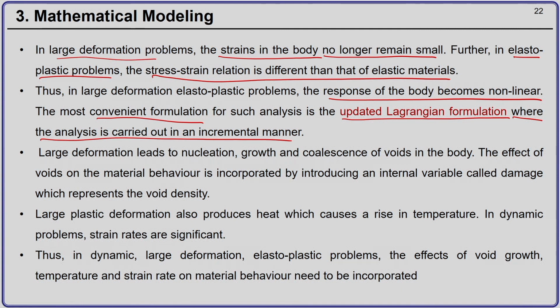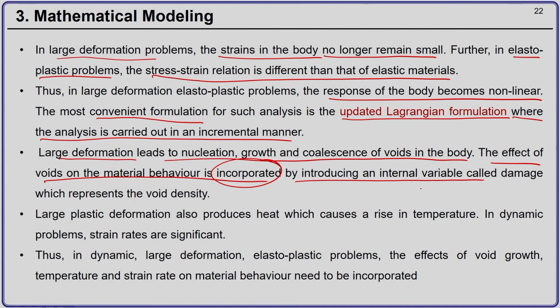So, large deformation also leads to nucleation, growth and coalescence of voids in the body. That was discussed in previous slides, and the effect of voids on the material behavior will be incorporated by introducing an internal variable called the damage, which will represent the void density. So, our damage will be represented by symbol D.